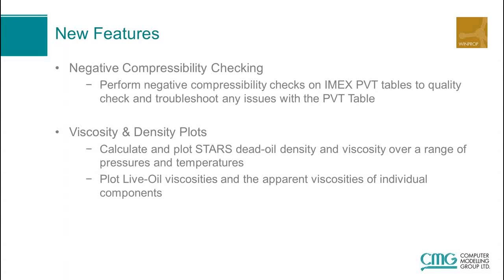And viscosity and density plots can now be plotted for STARS systems. If you have a STARS dead oil density and viscosity, you can now look at that over a range of pressures and temperatures. Previously, it was very difficult to do this because it was a dead oil; by definition, it's not going to have a multi-phase state. So now you're able to look at those calculations, as well as plot the live oil viscosity and the apparent viscosities of individual components.